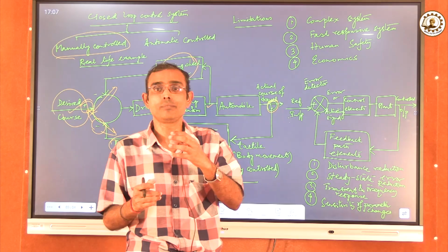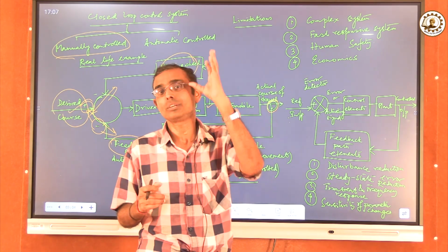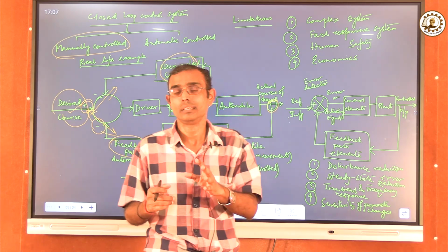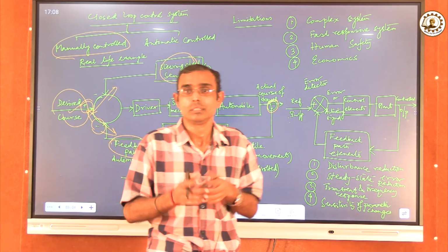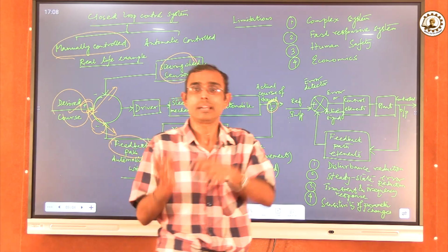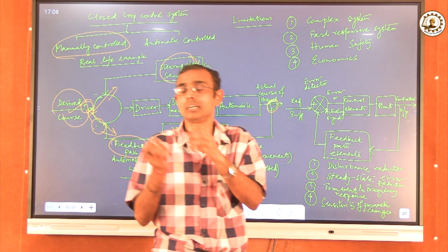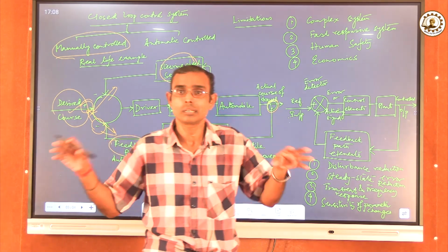And if that rate of traffic flow is incorporated in the control system of the traffic lights, that is red or green, that means in the direction where the traffic flow is more, it is supposed to have the green light for more length of time, and in the direction where the amount of traffic is less, the green light will be glowed for a lesser amount of time.